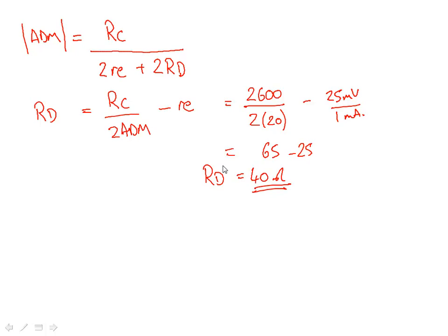We've now got basically the gain designed, the amplifier designed. The only thing now is the output stage. Now the output stage is formed by a DC level shift. Here we would have 1 volt DC and we want 0 volts DC. This is a current source and it's using the same degeneration, so this is pulling 0.5 milliamps, as per the spec. This is at VCC, which is 3.6 volts, and has no effect on this design, and this is at minus 3.6 volts VEE, and again has no effect.